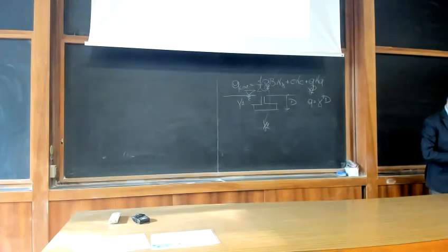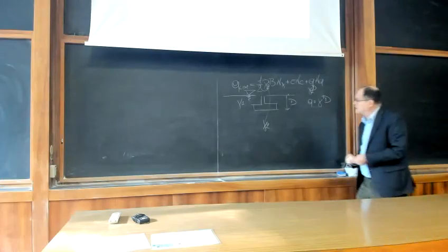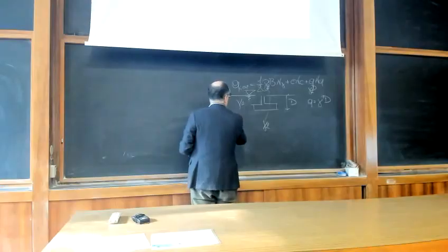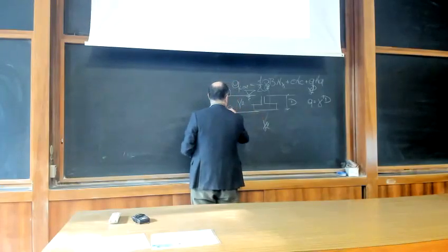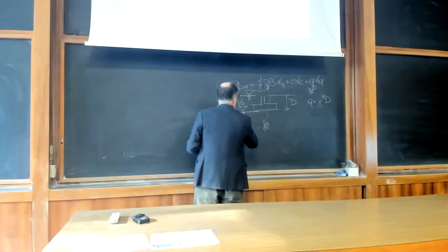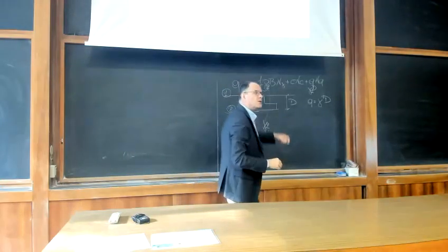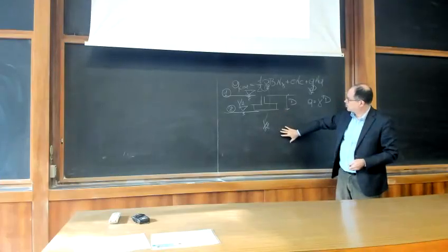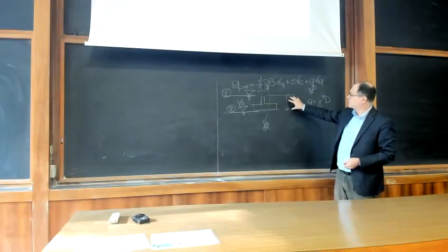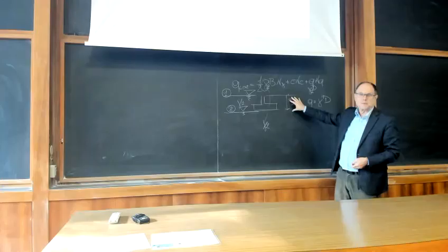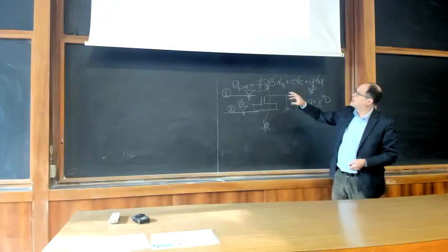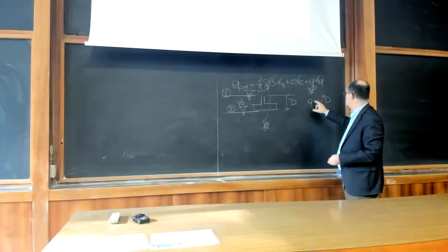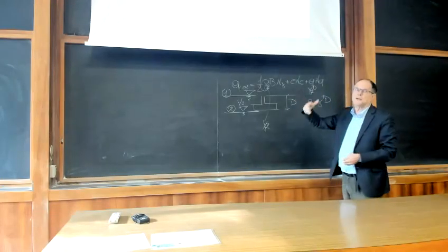If you have the second case, this was case 1, the case in which, case 2, your water table coincides with the bottom of your footing. So here, this soil is fully saturated, this soil is not. So you see, in case of q, you will use its gamma, not gamma dash, you will use your gamma, gamma 1, whatever it is.